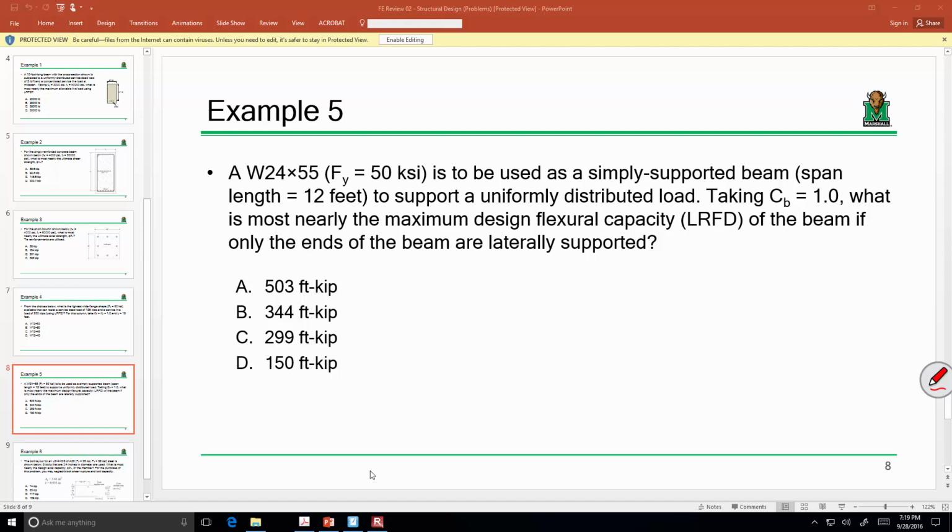Now, when we make our derivation, when we go through and do all the differential equations and derive all the stuff, one of the things that we do in our derivation to make it possible and make it simple is we say the moment is a constant. So you can imagine if you've got a big equation, you've got a constant, you can factor it out. That's technically not correct.